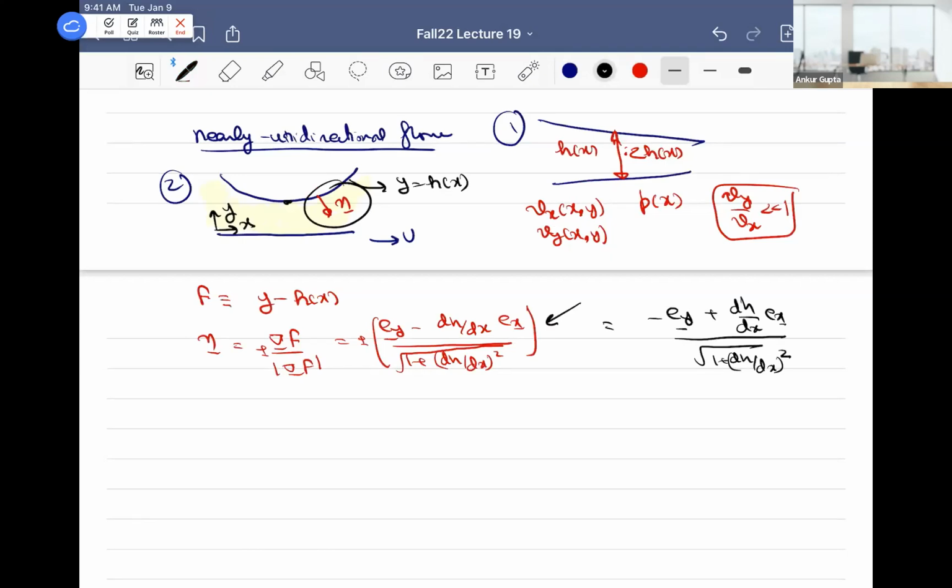For an exam, for instance, a potential question is that we might ask you to figure out the right normal direction or find a force using that normal direction. Generally students get the direction wrong or some steps become difficult. But the idea is to make sure you remember to point the normal into the fluid. That's the key part. And if you know the shape, you just write a shape function like y minus h of x and take a gradient.